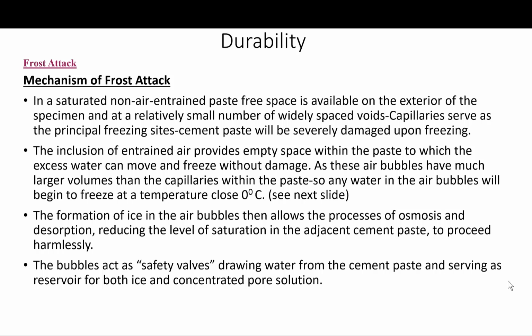Okay, in saturated non-air-entrained paste, free space is available on the exterior of the specimen, and a relatively small number of widely spaced air voids occurs incidentally within the paste or the concrete. So the capillaries in this case serve as the principal freezing sites, with the result that the cement paste will be severely damaged upon freezing. On the other hand, the inclusion of entrained air provides empty space within the paste to which the excess water can move and freeze without damage.